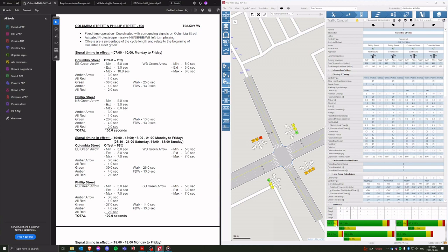You will notice, because of how we've calculated our splits, not every single one of these phases actually fills up each half here of our ring barrier diagram. That's fine. It's not a big deal at all. But if we did want it to show that, then we could make some adjustments to our splits here. So we could, for example, extend signal phase 2 for another 4 seconds here to fill it out.